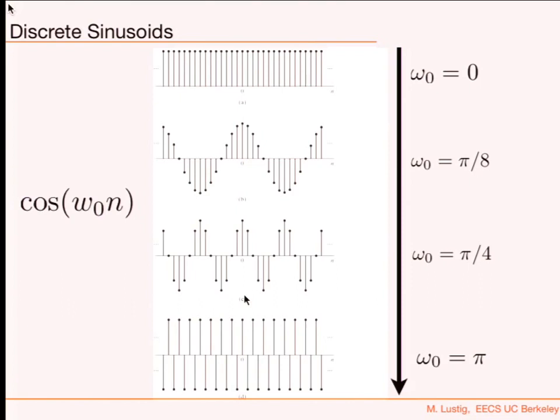Actually, if you look at sinusoids, they don't look like sinusoids anymore. They're different just because we sample them. But surprisingly, if we sample at a certain rate, then we'll be able to recover this sinusoid. So this sinusoid is still recoverable. Okay, we can recover it.